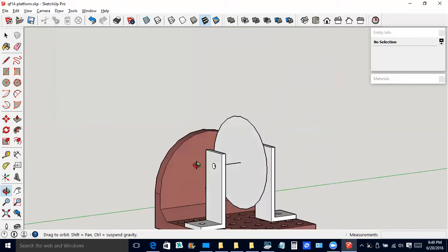Now, what I want next is to make a hole in this circular plane right here, and it's going to be a 0.078 inch radius hole, clearance hole for a 6-32 screw. Okay. Circle tool. Here, we'll just drag that out a little bit and click, and then you don't have to go down here and click down here.